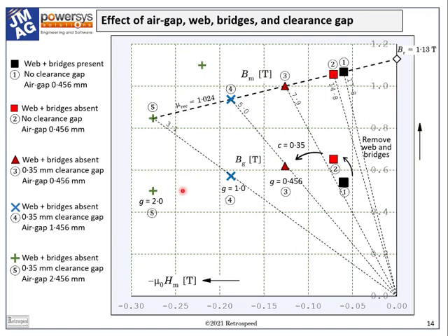It's not safe to draw general conclusions from this small study about the wisdom of such a configuration. There's something in the idea, for sure. What appeals to me is avoiding that shocking waste of 20% of the magnet material, although that figure itself is rather arbitrary because it's a consequence of the original choice of the thicknesses of the web and the bridges, and those thicknesses were simply starting values, not the result of any detailed analysis.